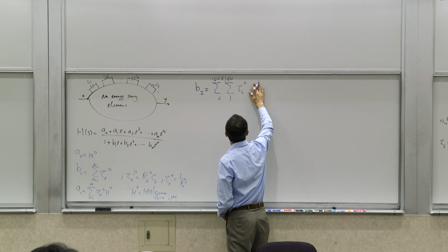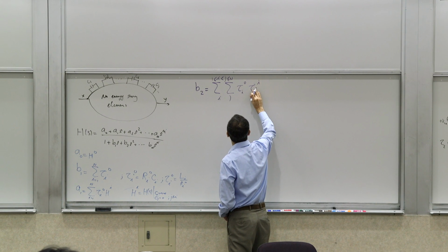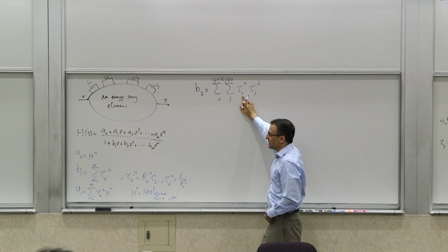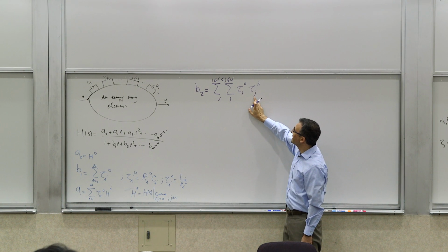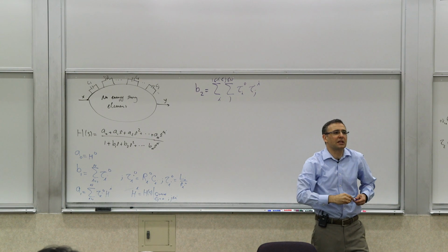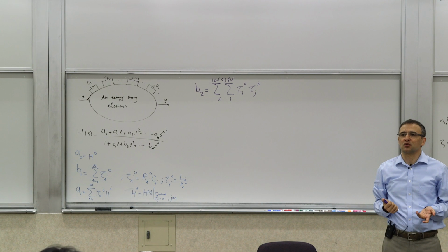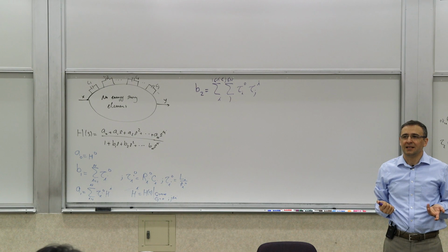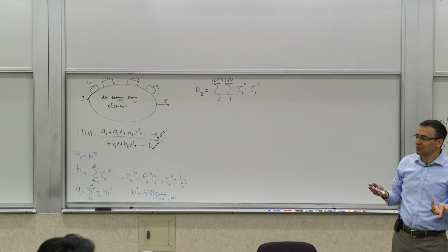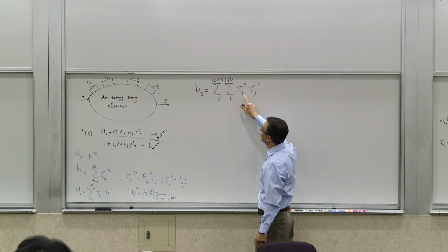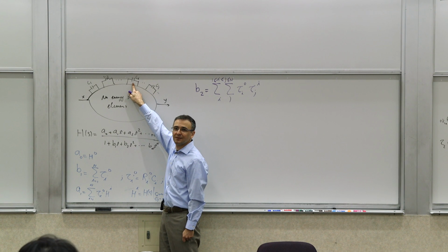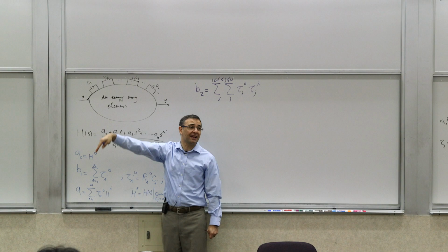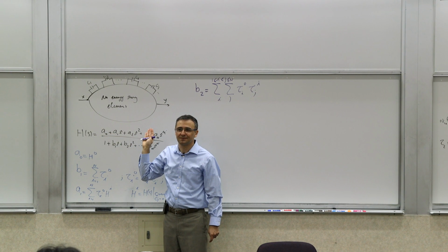Now, if we've thought about our notation and if we've been clear about the meaning of things in our notation, well, this is clear. This is tau i0, right? What is tau ji? What does it mean? What do you think it means when you have a superscript i? It's the infinite value element i. Yes. The time constant associated with element j when element i is infinite valued. And everything else that's not listed is still zero valued.